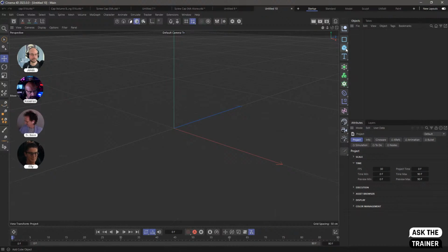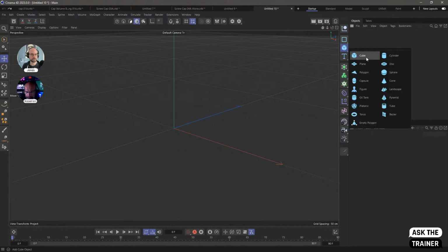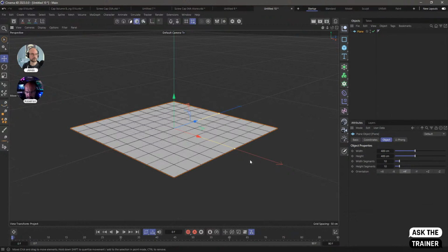So quickly, I want to give you an overview of certain things. I'm going to talk about polygon modeling mostly, and certain important aspects of it. I'm reading my cheat sheet over there, that's why I'm not looking directly at you. So a couple of things about subdivision surface modeling, and a quick overview of how it works. The way I usually present this is not a cube, but a plane. You create a plane, and let's activate the lines, which is something you're going to see me doing quite a bit.